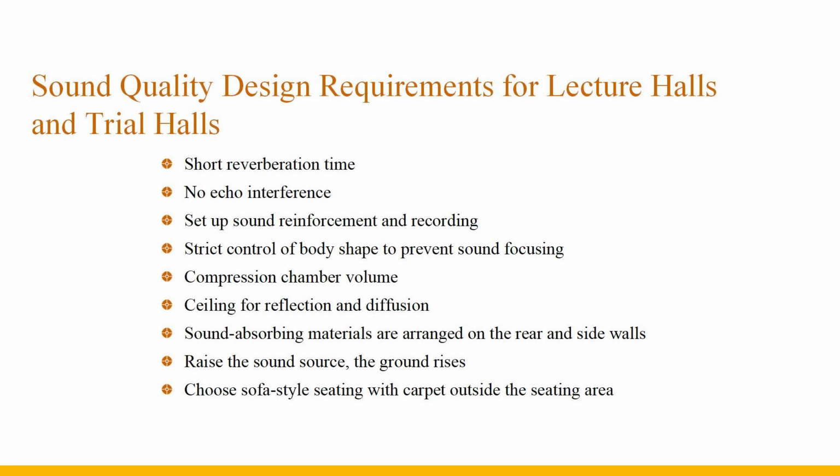Both the lecture hall and the trial hall require high language intelligibility for indoor sound quality. The language sound source may come from different parts of the hall, and the sound source itself requires good listening conditions. Therefore, the reverberation time is required to be short and there should be no echo interference. Due to the need for recording, sound reinforcement and recording equipment should be set up.